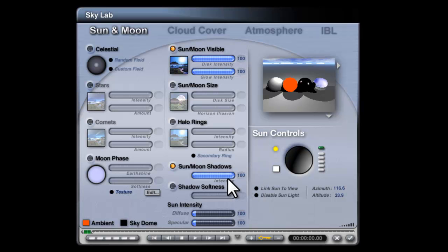The other reason for turning that up higher is that it affects the render time. Because it essentially lets light travel through solid objects, it means it's simulating more rays to be calculated, because a ray that might have stopped on this surface then stops on that surface and also travels a certain proportion of it, dependent on this setting, through the object and then reacts to other things. So you can imagine it's like turning all your objects a bit transparent, which creates a lot more work for the render engine. So set that at 100 wherever possible.